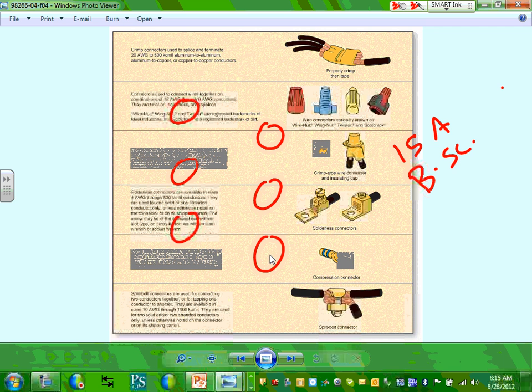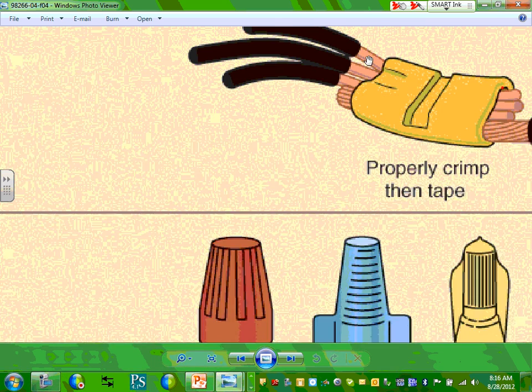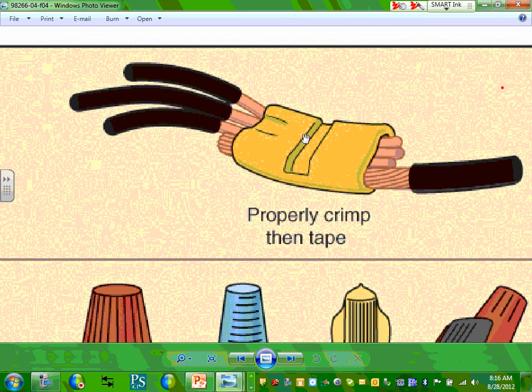When we do tours, guys, you're going to see, and I know Jeff laughed at me about the twisted wire nuts here, but you see how important these ones are when we tap conductors. These have become very, very important when you tap a 500 kcmil and you need to take 4 out from it. What's the alternative, guys? You're going to be project managers. What's the alternative? Now, engineers don't like the tap rules, a lot of engineers don't like them, because taps are not reliable. If the feeder trips, you trip 4 panels.